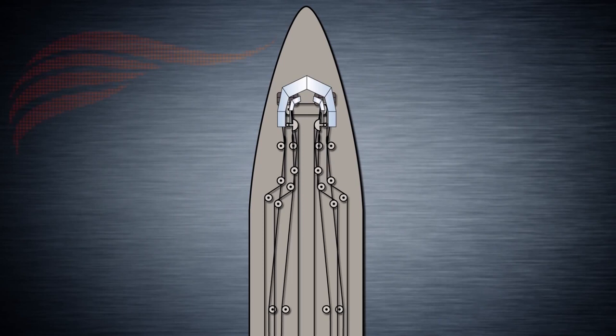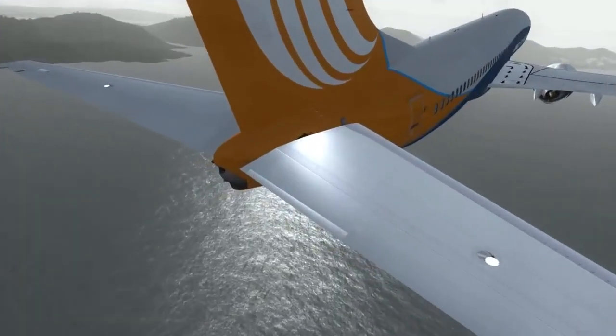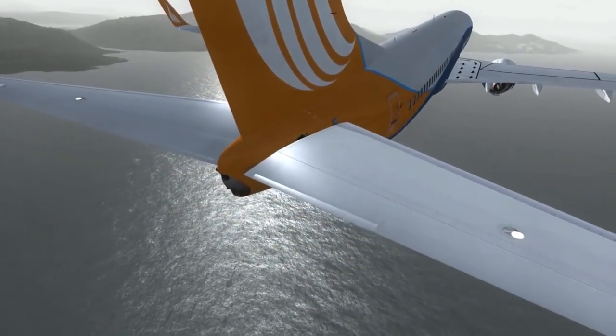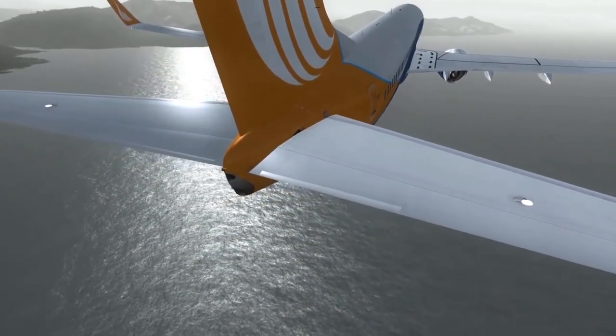In this condition, when 100 pounds of force are applied on the control column, the elevator moves 4 degrees. In a total hydraulic failure emergency situation, this amount of deflection is sufficient for a safe landing flare. The elevator PCUs also limit the amount of elevator travel.